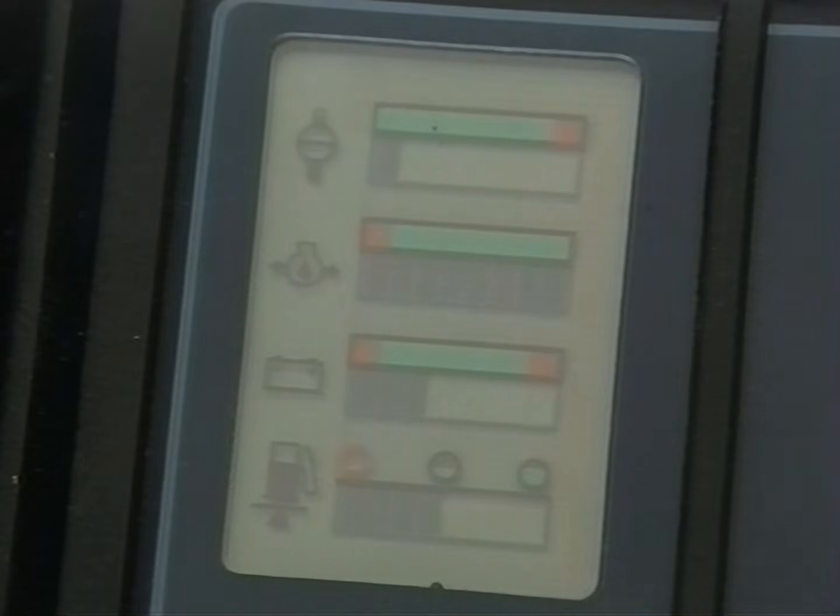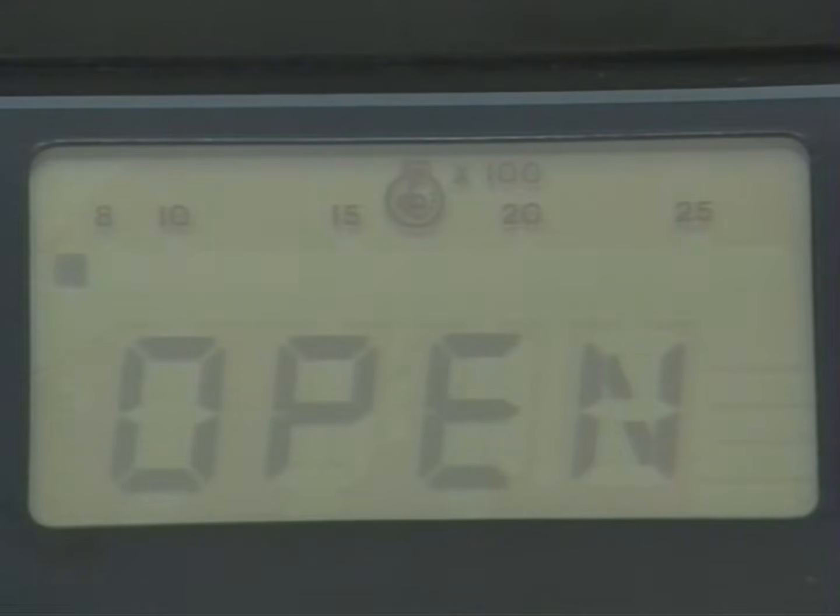The electronic instrument panel uses a different set of displays to indicate a concern in the EIP sender circuits or in the EIP itself. Let's look at one of these concerns: engine oil pressure sender circuit open. When the oil pressure sender circuit is open, the EIP senses that the voltage signal has been interrupted.